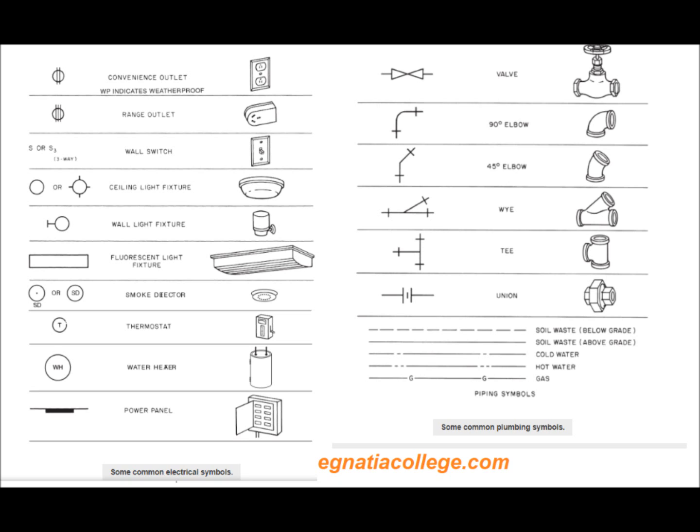Mechanical systems, plumbing and HVAC, heating, ventilating, and air conditioning, are not usually shown in much detail on drawings for single-family homes. However, some of the most important features may be shown. Piping is shown by lines. Different types of lines represent different kinds of piping. Symbols for pipe fittings are the same basic shape as the fittings they represent. A short line, or hash mark, represents the joint between the pipe and the fitting. Plumbing fixtures are drawn pretty much as the actual fixture appears.